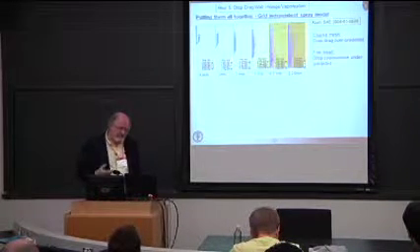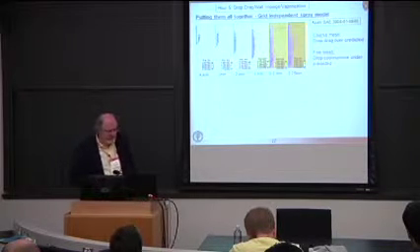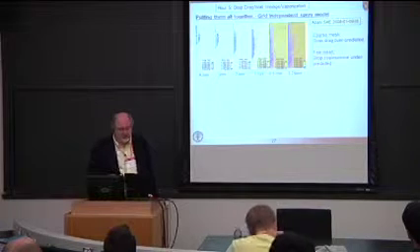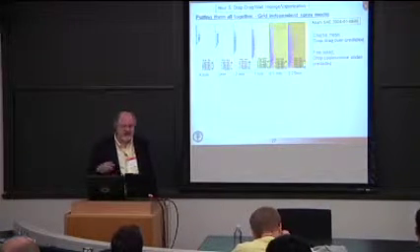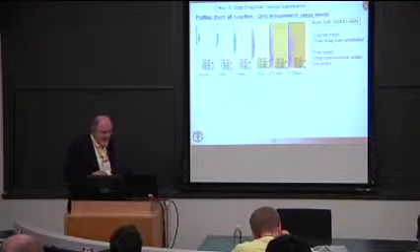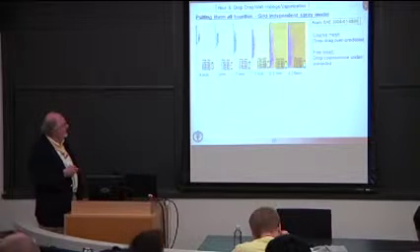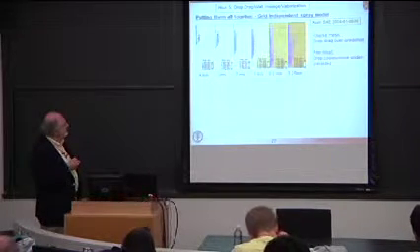We discussed vaporization, breakup, collision, coalescence, drag, wall impingement. But there's more to it, as I mentioned earlier. When you put this into a CFD code, and remember that all of these things are sub-grid scale models, what you find, disappointingly, is that the results depend on the mesh size. So for example, here, I injected all those classes of drops.